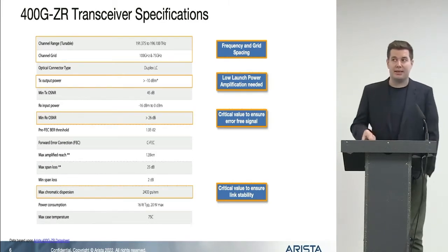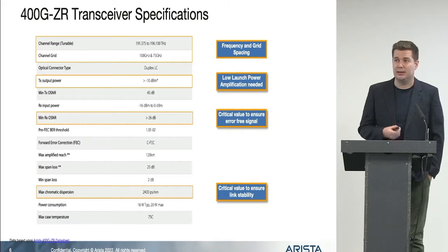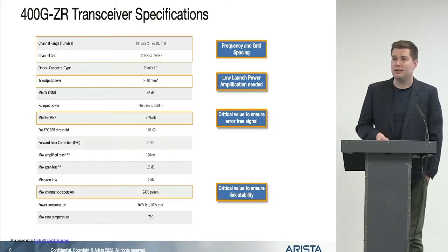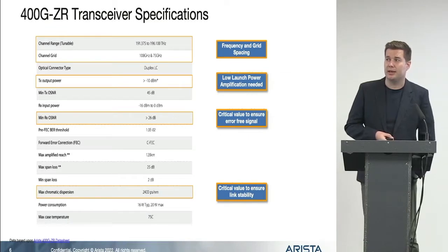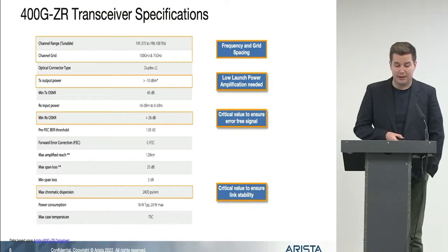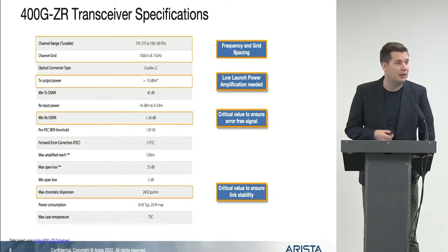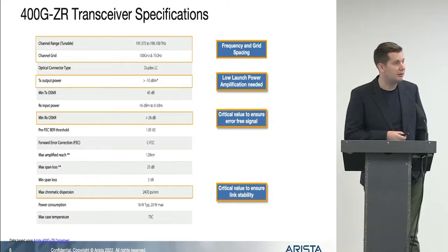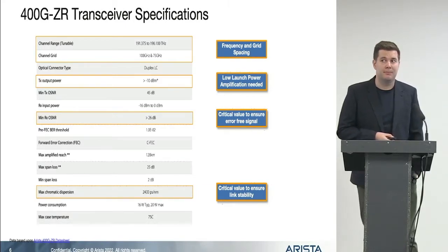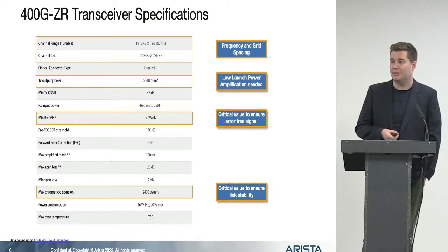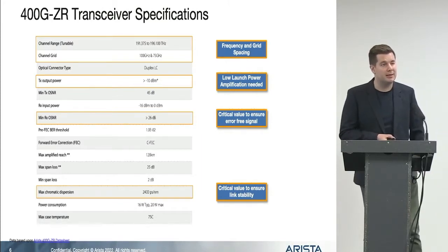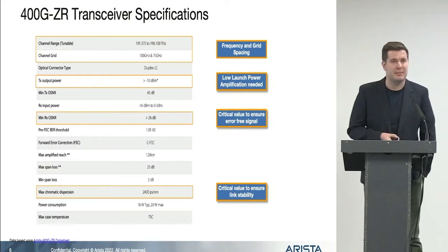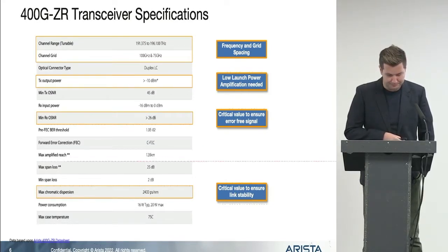And you'll notice actually the transmit power from the transceivers we have available today is relatively low power for a long reach connection. So kind of looking around minus 10 dBm. And as you'll see, that may require boosting for longer reach. That's typically because of the form factors this standard is going in. So the form factors of typically QSFP-DD and OSFP have thermal limitations, they have cooling limitations. That really explains why the transmit power is maybe lower than you would expect.